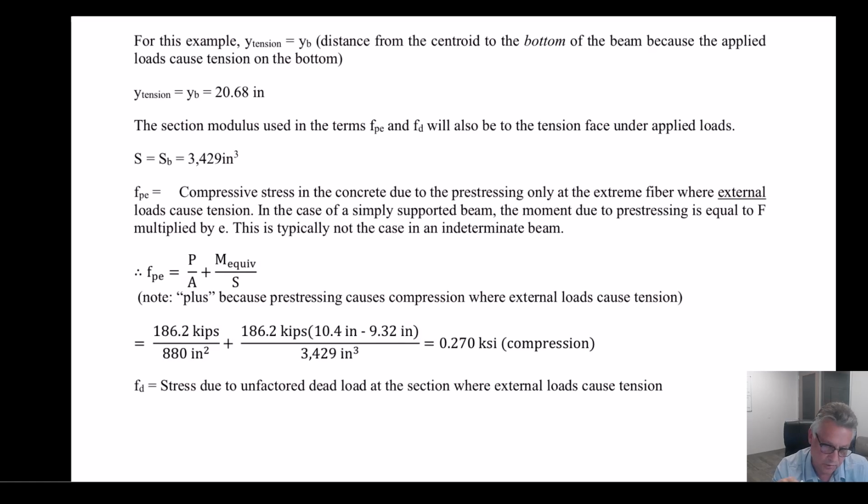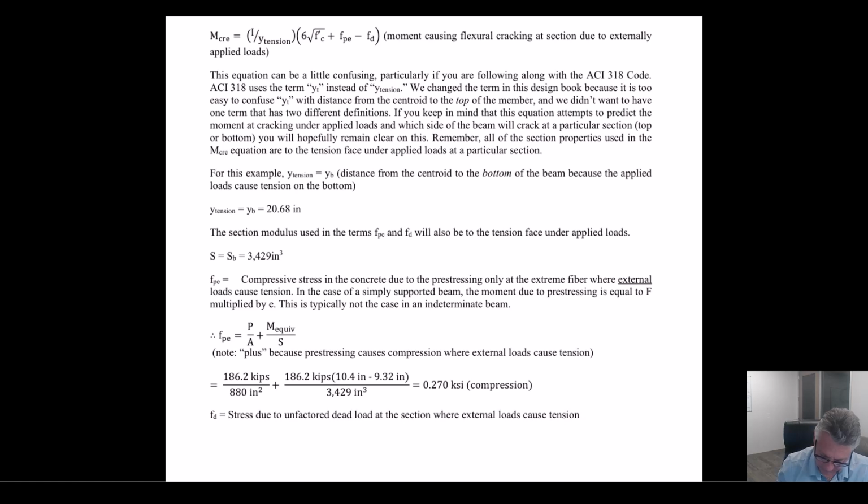So here, you're going to do F times E. In your homework, you're going to be able to do F times E because I'm giving you a statically determinate member there too. Just be careful. And you UCLA students, I put this on the final, and I give you two choices. You get to calculate the equivalent moment in these equations. I give you enough information to make it the primary pre-stress moment, and I also give you enough information to choose the equivalent moment due to a moment distribution. That's the one you need to pick if they're different. If they're different, it's because it was statically indeterminate. So, okay, hopefully I've confused everybody enough with that.